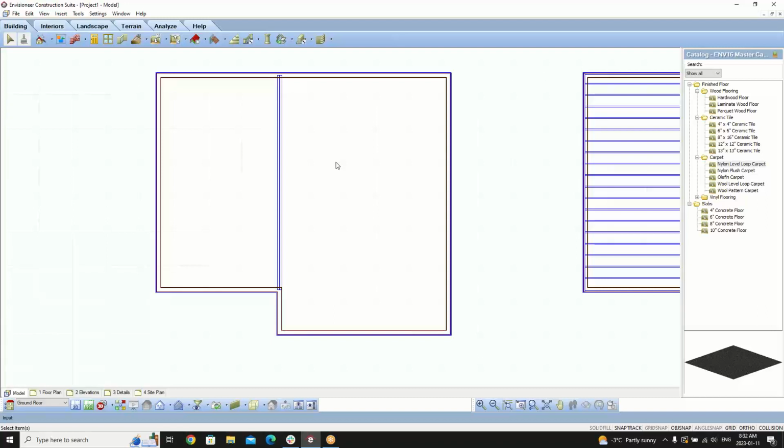The floor tool can also be used to add in framing by specifying the floor as a frame floor and then assigning the correct members to the floor components. The floor tool adds in a floor finish like tile, carpet, or hardwood, and then it can be elevated to the right height so that the material would sit on top of the floor assembly that you've added in.